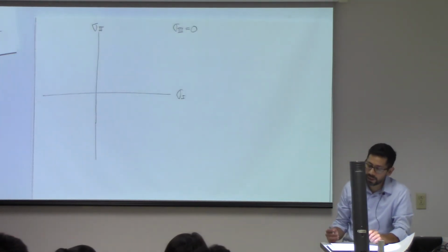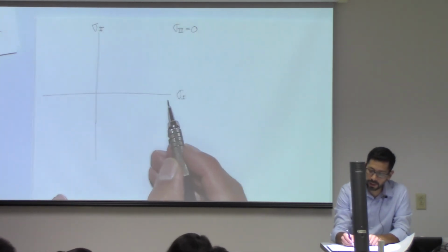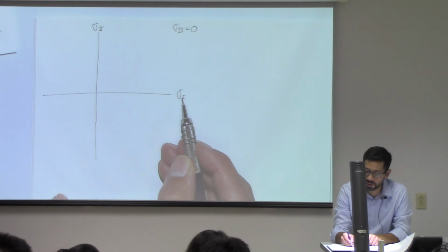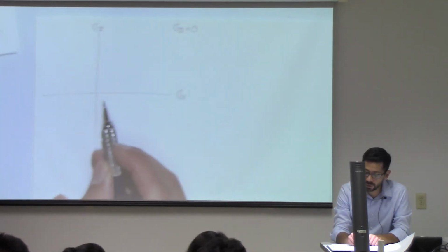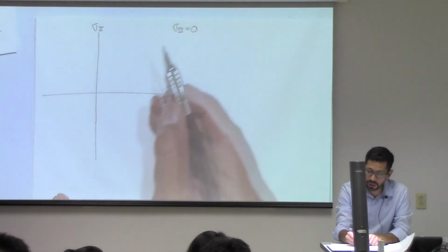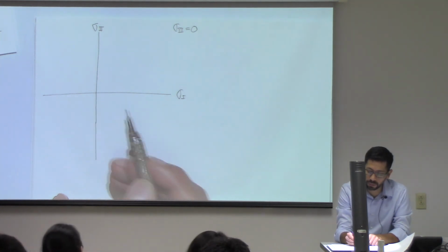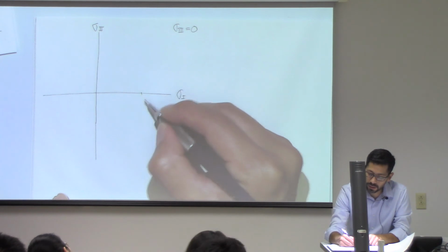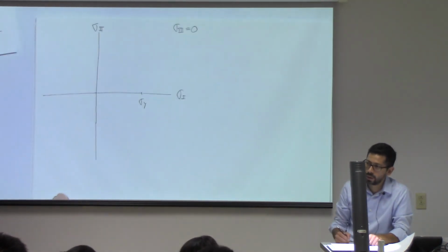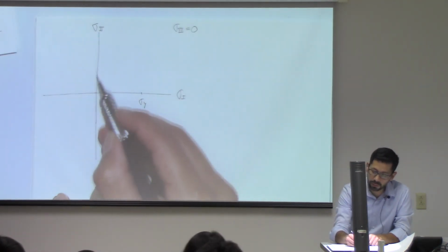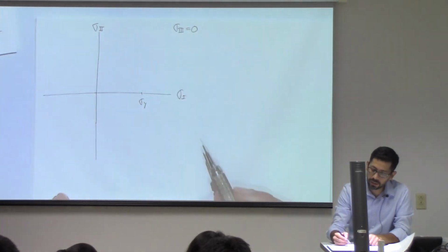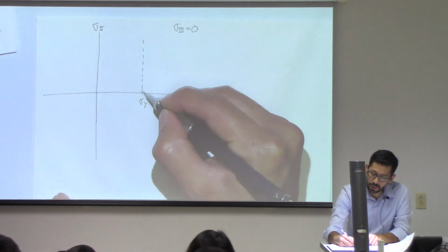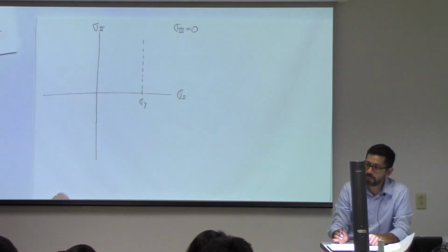So if I apply the Tresca criterion, and let's say sigma 1 Roman is the maximum principal stress and the other two are 0, that will be a point over there. The maximum value I can go, in this case, is sigma y, right? Even if I increase sigma 2 and sigma 3 remains 0, I can go up to a limit.